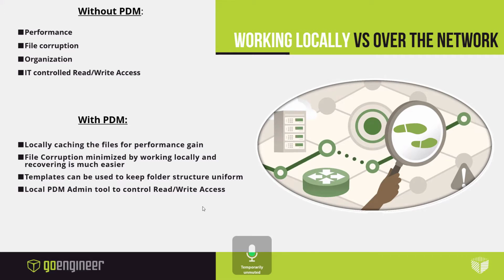Is everything getting pushed over? No, only the changed files are actually pushed. So if you check out an assembly with hundreds of parts in it and you modify 3 or 4 of them, you're going to be checking back in the assembly, the sub-assembly, and the 3 or 4 modified parts. So you're actually reducing the traffic there as well. Okay, so that's going to alleviate a lot, especially if you've got quite a few CAD people working in the PDM system. That could be a significant increase in your efficiency on your network.